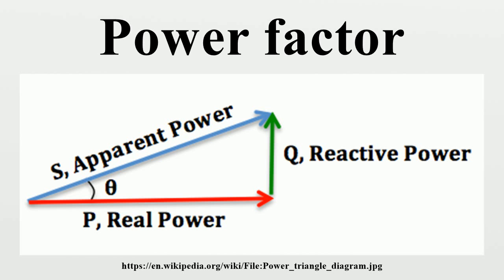Definition and calculation. AC power flow has three components: real power or active power, expressed in watts; apparent power, usually expressed in volt-amperes; and reactive power, usually expressed in reactive volt-amperes. The VA and VAR are non-SI units mathematically identical to the watt, but are used in engineering practice instead of the watt in order to state what quantity is being expressed. The SI explicitly disallows using units for this purpose or as the only source of information about a physical quantity. The power factor is defined as the ratio of real power to apparent power.